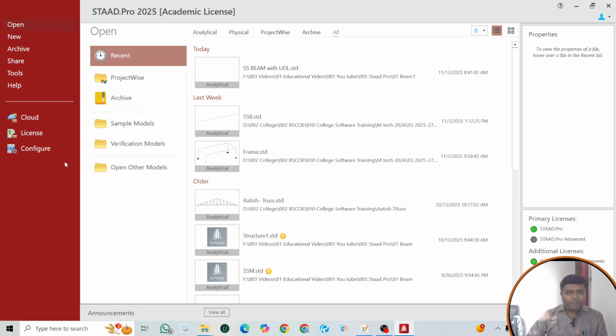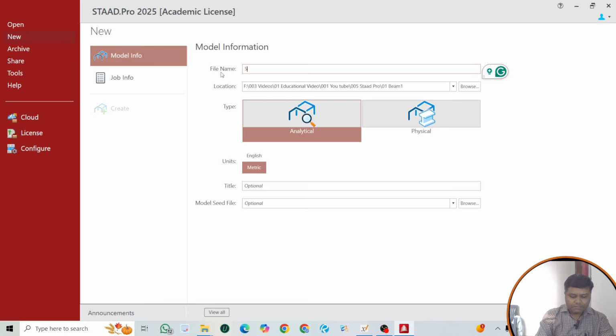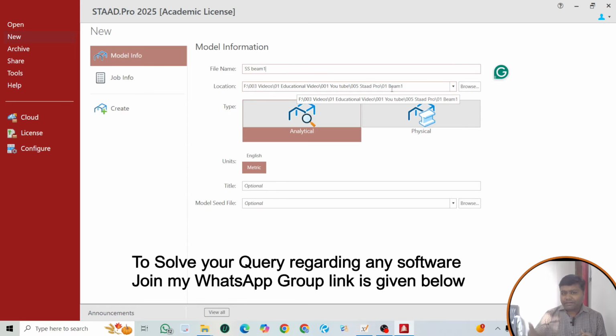Now the next step is to just click on the new. Now we are starting the new project, so just click on the new and give the name of that project. Suppose I'm considering simply supported beam, let's say one. And then we have to choose the location of that project, meaning where we want to save it. Here I am selecting videos, educational videos, YouTube videos, STAAD Pro training and beam. This is my folder path where I want to save my project.